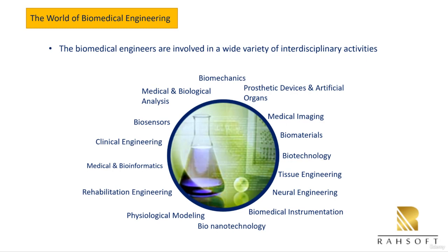Biomaterials looks at the materials that are being used, particularly for prosthetic devices and organs, not only to help create new biomaterials that will be more effective than the ones we have, but to figure out which ones are more applicable in different circumstances. You don't want to have something like a ceramic, which is easily shatterable, for something that needs to be very bendable. However, you don't want to have something that's very inert if it needs to interact with the environment. And these are things that need to be taken in when researching biomaterials.